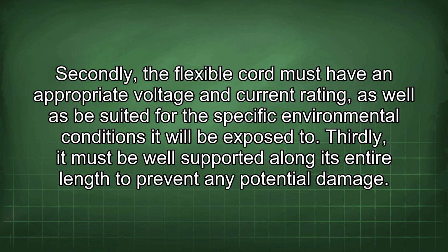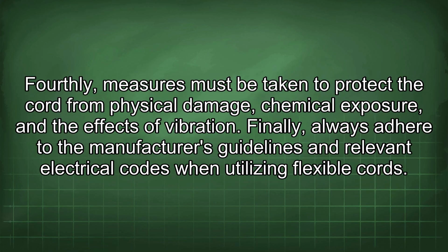Thirdly, it must be well supported along its entire length to prevent any potential damage. Fourthly, measures must be taken to protect the cord from physical damage, chemical exposure, and the effects of vibration. Finally, always adhere to the manufacturer's guidelines and relevant electrical codes when utilizing flexible cords.